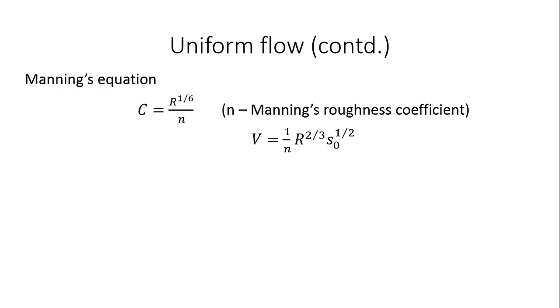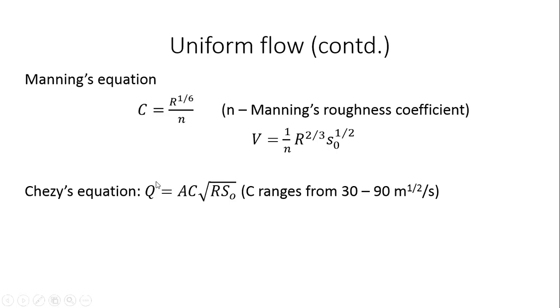So this is something that you should remember. Many years later, you should remember Manning's equation. So V is simply 1 by N R to the power 2 by 3 S naught power half, right? So we have these two expressions, Chezy's equation and Manning's equation, for estimating the velocity in a channel that is undergoing uniform flow, right? We can easily convert this to flow rate Q.